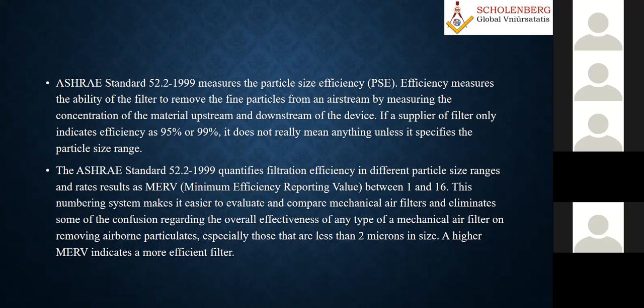If you visit any factory, there will be a testing area, test measures, a controlled environment, and quality control. Though the factory issues the test certificate, it all depends on you as a designer, as a consultant. You can always waive the inspection, or you can insist on going to the factory and inspecting it. It depends upon your jurisdiction. As a design engineer, for major capital equipment, I prefer to go and stand there and witness it.